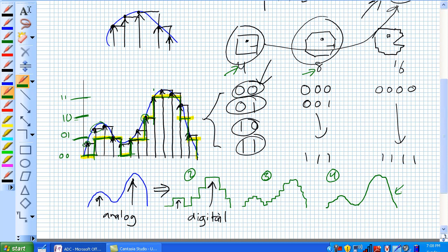Okay, so you see what's going on there is the more bits you've got, the closer the digital representation is to the analog. Additionally, you could be sampling this at a faster rate. Notice particularly this area right here where it's a pretty steep slope. You would probably want to have faster samples there because notice we're only getting that and that right there on the edge. Whereas this guy with 4 bits, you're getting a better sample. When it's changing so fast, you want to sample it a little bit more. So how do you get a more accurate representation? Increase the number of bits that you are trying to categorize it into and sample it a little bit faster.